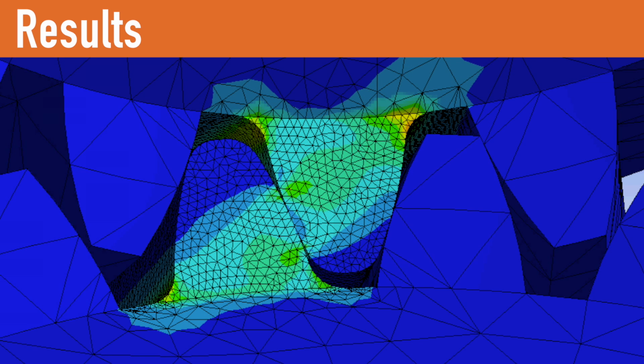Stress distributions near the point of contact between the teeth are likely to be inaccurate. This is because a bonded contact had to be used in order for ANSYS to converge on the solution. However, the total force transfer is the same, and the stress distributions near the root of the teeth are likely to be accurate.